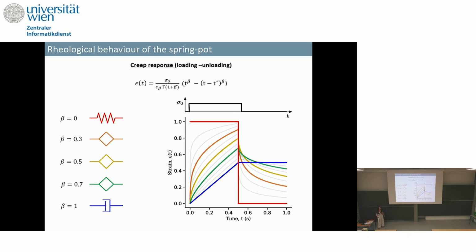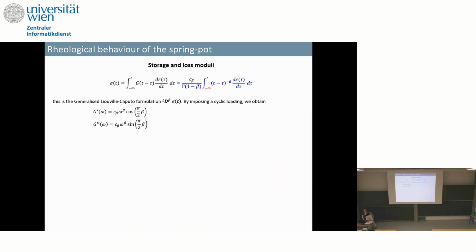That is this one. The same study you can do for the storage and loss moduli. One little thing to keep in mind is that in this case, as before, we need to integrate from minus infinity because that's a cyclic loading. And that's not called Caputo's derivative anymore. That's called the Liouville-Caputo formulation. So that's a different formulation.